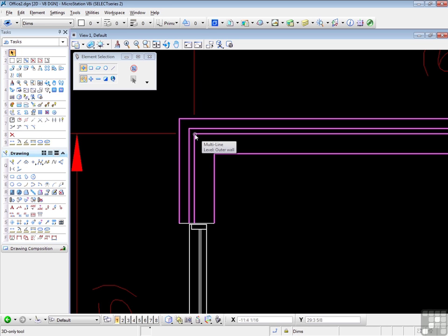And this is simply because when constructing the building, the exterior block walls will be placed first. The brick veneer exterior skin will be added after the roof is on and the windows and doors are installed. This is why the dimensions are to the exterior face of the block, because the mason laying the block needs these dimensions first. This will affect how we define our multi-line definition. To be precise, we need this line to be our working line when we place these exterior multi-lines.